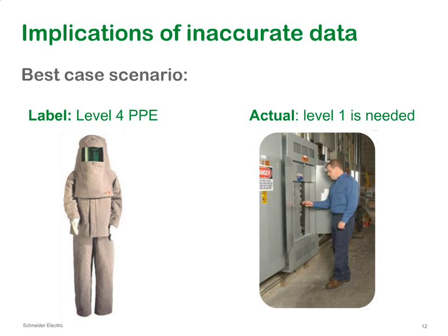So moving on, the next issue that you have to be concerned about dealing with arc flash analysis is the fact that if the data coming in is not accurate, it will provide wrong answers to you. So we have a kind of garbage in, garbage out situation, and the result, if the study is not performed correctly with accurate data, is that we could have too much PPE on the person or too little PPE on the person.